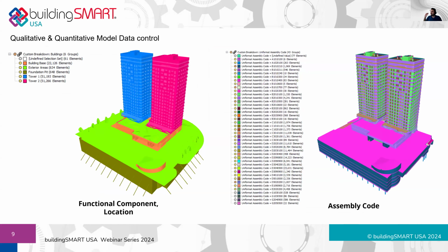Of course, this could be, from the assembly codes, the basic classification properties, to the functional component location, to even, we use it, let's say, for the reinforcement density population from some Excel tables that were produced by the structural designer that were completely outside of the BIM, but simply they could refer to the certain type of the element, let's say a column with a certain mark, that should be attributed with a certain property that they already calculated when it comes to reinforcement.